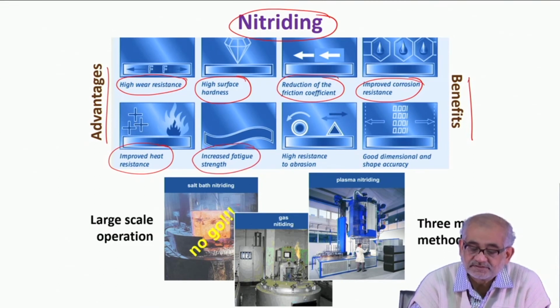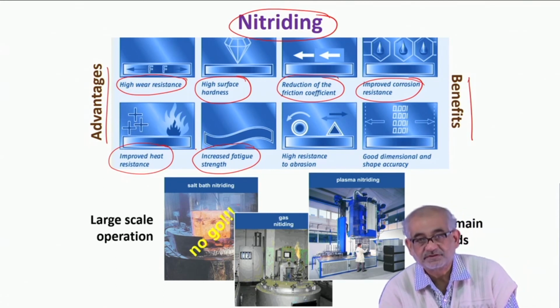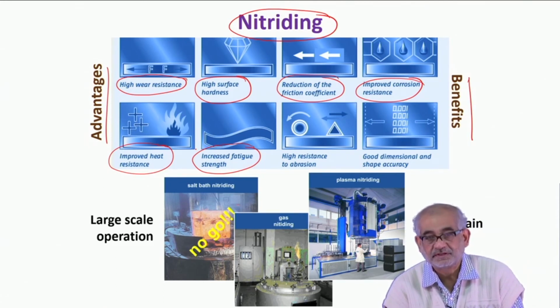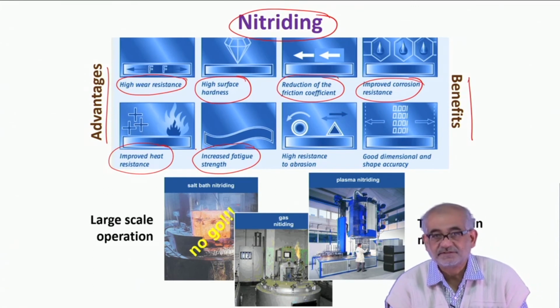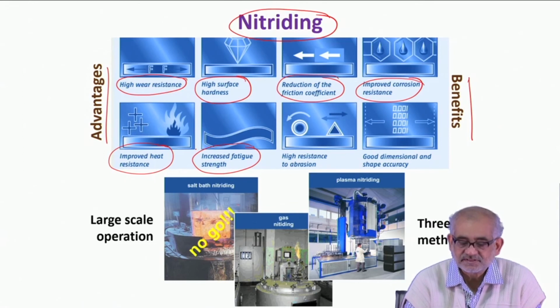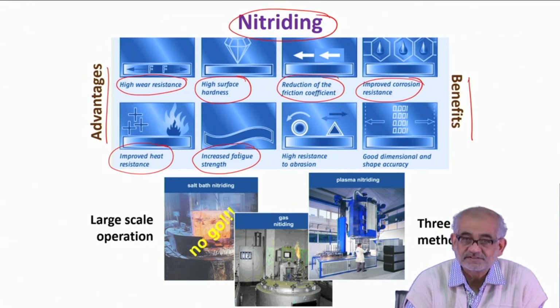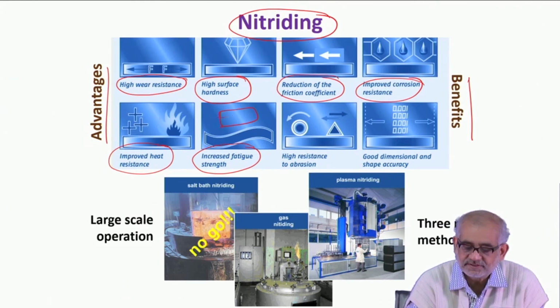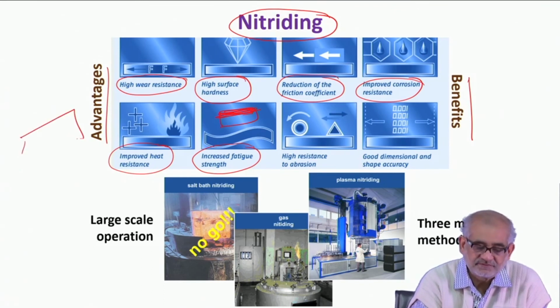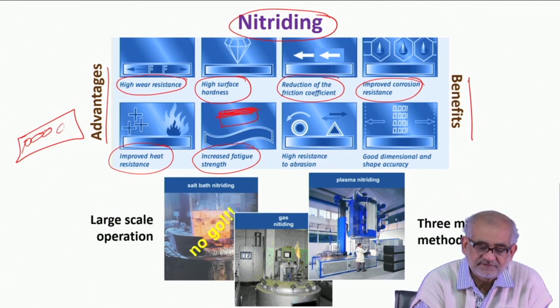There is also an argument that though there is no supersaturation, no formation of martensite, which actually causes expansion of the matrix and creation of residual compressive stress, even in nitriding, though such mechanisms don't exist, yet if we have a rich nitride layer on the case, these nitride compounds actually have a higher lattice parameter. So in the matrix, which is BCC iron, if you produce nitrided phases which actually are having a larger lattice parameter,